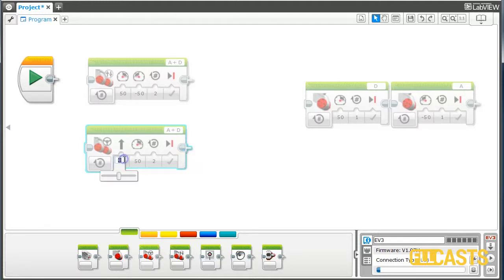That's interesting, because we can say that we would like one of the motors to move faster than the other, and in this way to steer the whole robot. Now it takes some experiments with this block in order to learn the values. What does the value 100 mean? It means that one of the motors is moving in the opposite direction than the other motor.